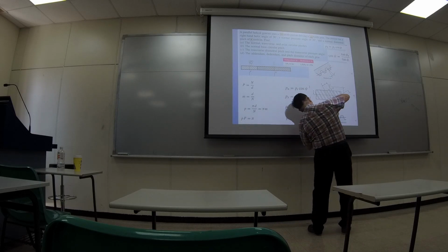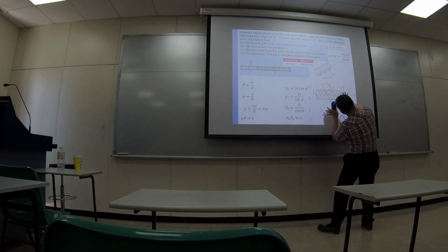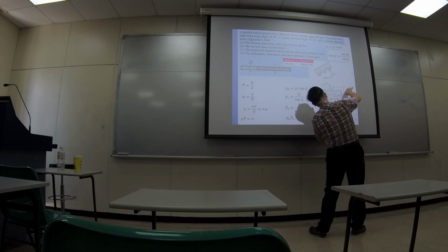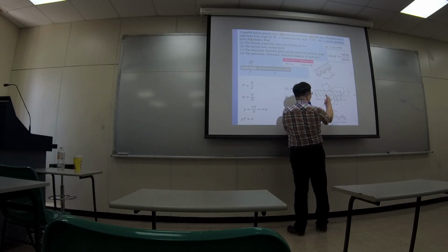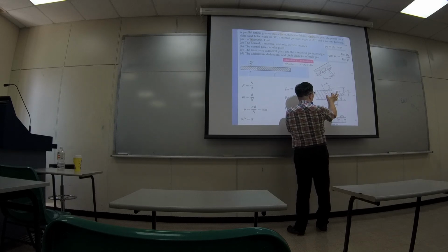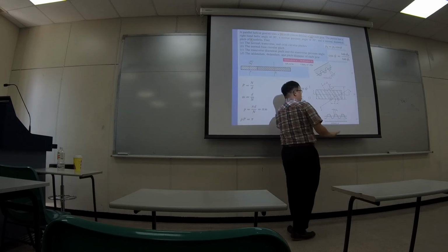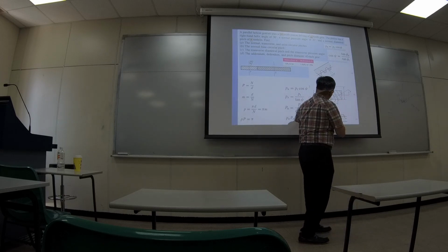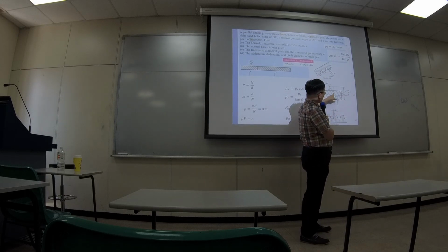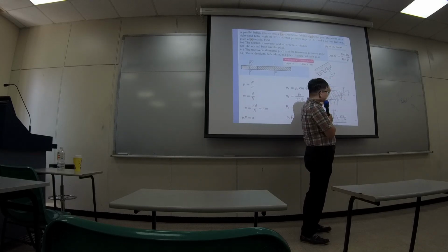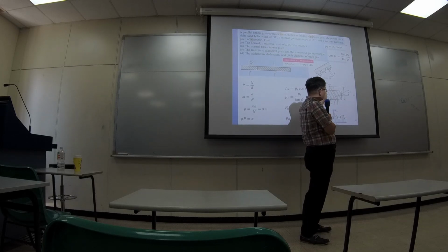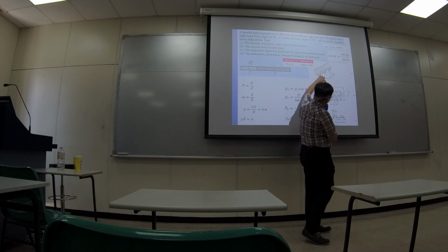When you tilt in this way and observe the teeth, it looks like a spur gear. So if you tilt this way and study from one edge of the teeth, going up and down, and then move to the other one, the distance right here will be the pitch along this direction. Since in this direction the way you take the walk is perpendicular to the direction of the teeth, they use Pn. N represents normal. So it's normal to that direction. Over here it's called the P normal, Pn.